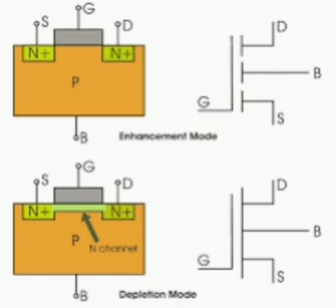If VGS equal to VP, then the depletion region fully occupies the channel and the channel becomes pinched off. VP equal to A square QND by 2 epsilon minus V0 for P plus N junction diode. For P plus N gate channel junction, VP equal to A square QNA by 2 epsilon minus V0 for PN plus gate channel junction. When VGS is varied from 0 to VP, RDS varies from RDS on to infinite.